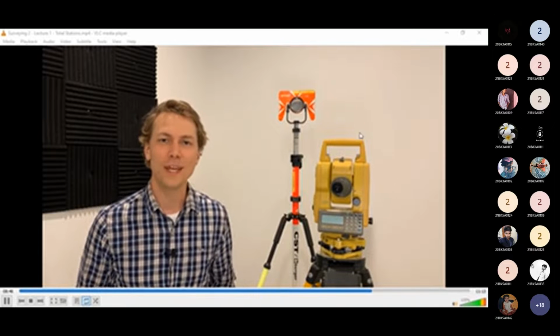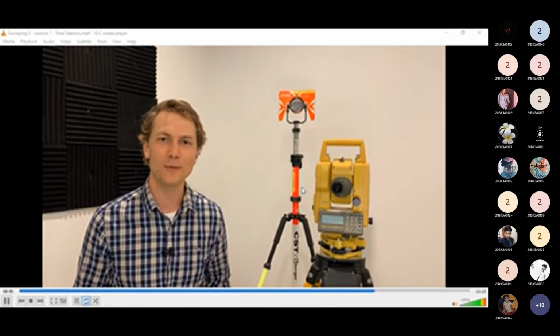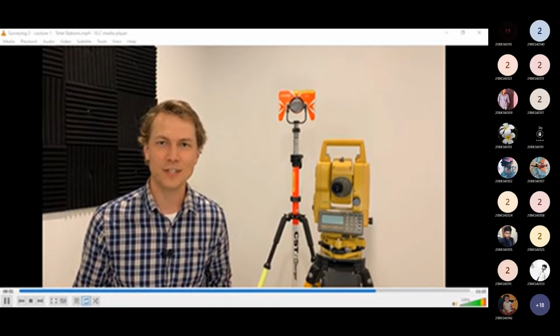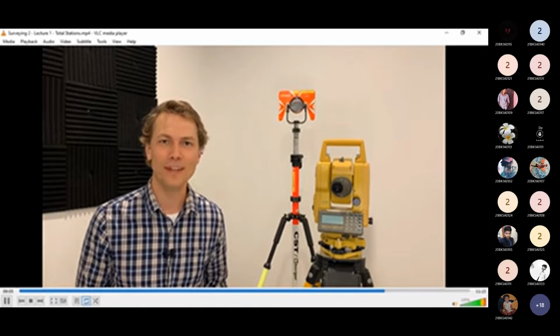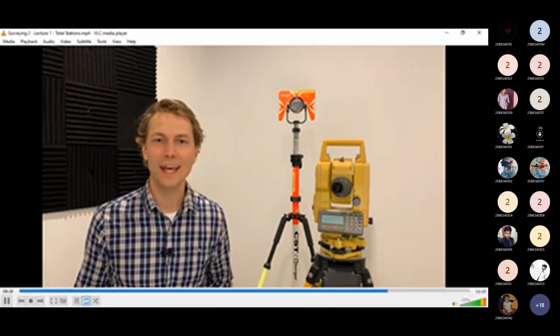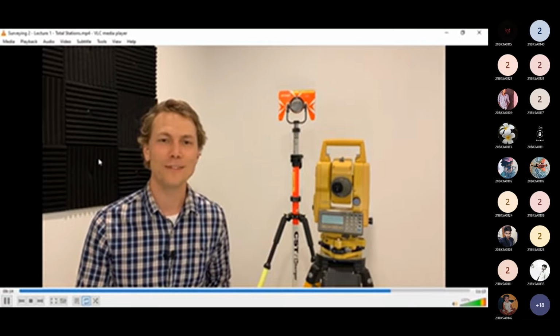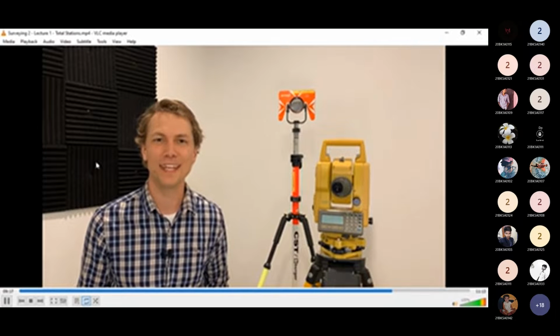First, the software helps you locate your instrument within a coordinate system using a 2-point resection for a total station and a localization for a GPS rover. No more doing hand calculations to try and find your occupy point. With your instrument location mapped, you can digitally collect the northing, easting, and elevation of each point in your survey. And you can see these points in a map view. And then after collecting all your information, export into another software such as AutoCAD or Civil 3D.